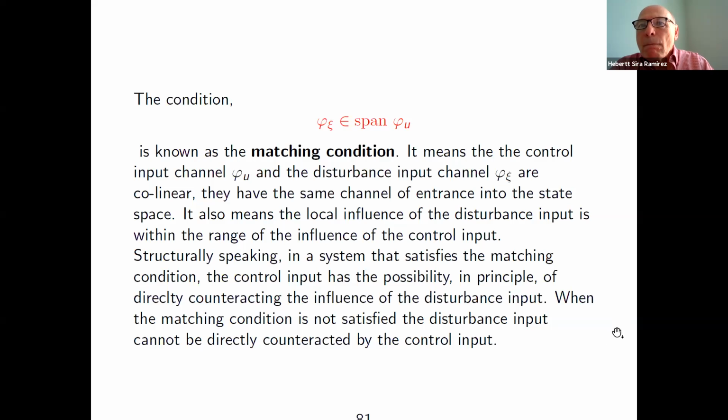Because to decouple disturbance from state is an order of magnitude more difficult. So that's where all this discussion came in about matched or unmatched. You can discuss all that if you have an accurate state space model. But in engineering practice, many times you do not have a very accurate model. Therefore, the discussion in state space about the matchedness condition is of little consequence in practice.